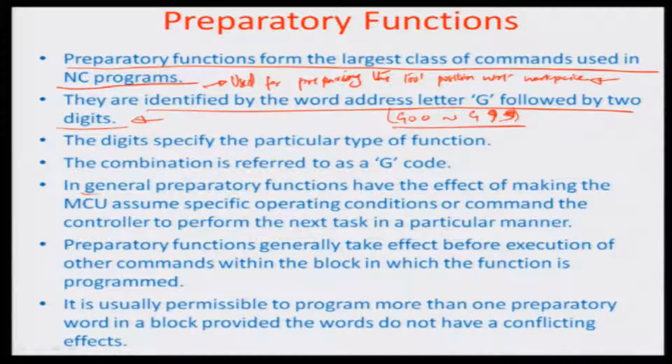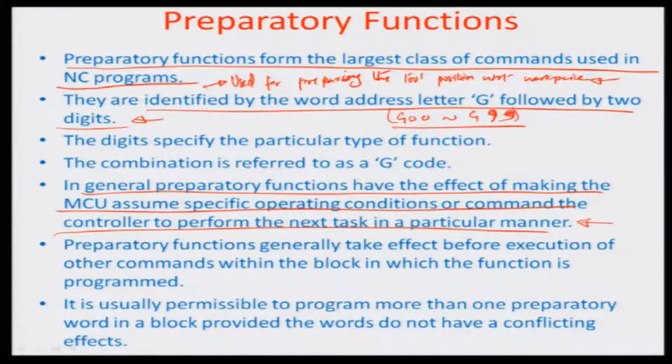And this position has the definition of all the metric units or systems, and whatever the measurements are in, whatever the relative motion is in, whether it is incremental or absolute, all those definitions should be contained typically within the preparatory functions. So, in general, the preparatory functions have the effect of making the MCU assume specific operating conditions or command the controller to perform the next task in a particular manner.